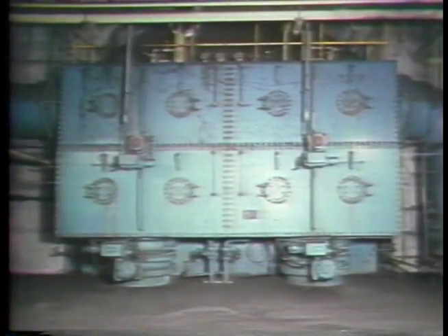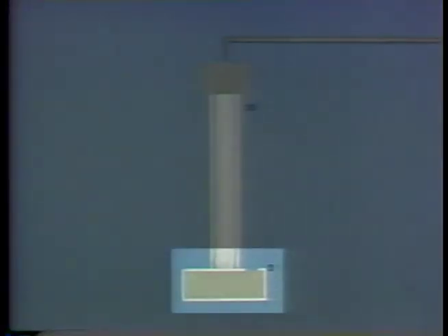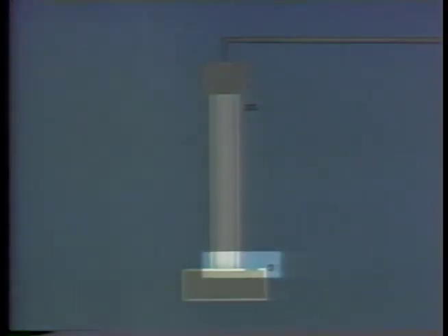Another common use of a mercury manometer is to measure vacuum in a condenser. It looks a lot like a barometer, except that one end of the manometer is connected to the atmosphere, while the other end is connected to the condenser. The scale reads from 0 inches of mercury at the bottom to approximately 30 inches of mercury at the top.